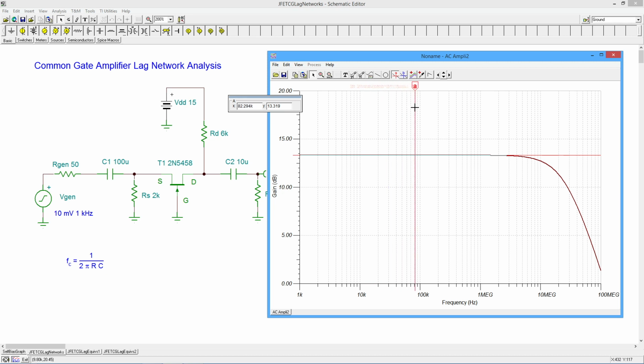All right, so 13.3. Now I have to find my 3 decibel down point for the system, F2. So that's going to be 10.32 basically, right? 10.32 dB is what I'm looking for. It's going down, it's going down. There it goes. Oops, I think I just missed it. Back up one. Okay, right there. Depending on exactly where you go here, it's probably in between, whatever, close enough. Okay, let's call that 26.1 megahertz.